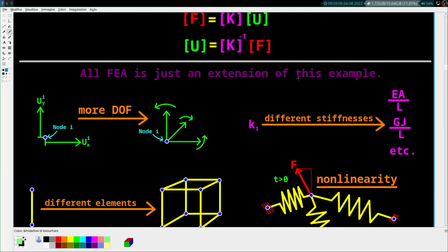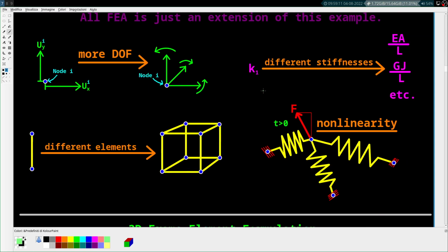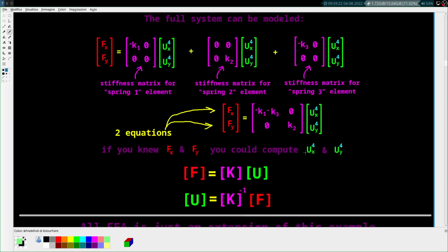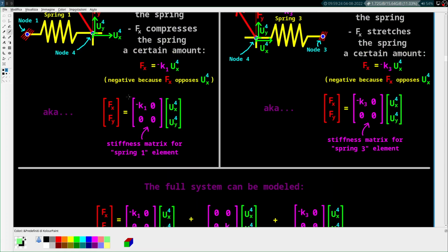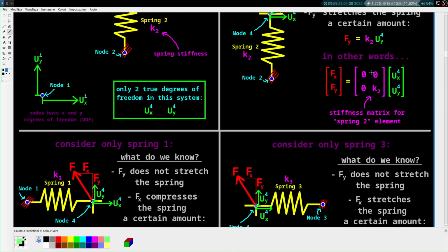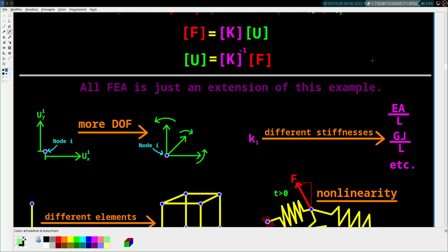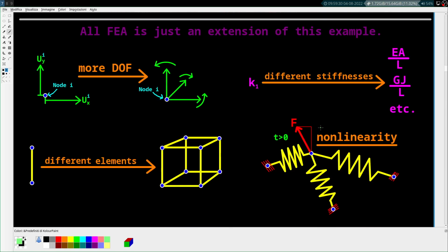So that's saying that if we were to break up the force into pieces, so if it's a 100-pound force, we took it in 10-pound increments, they would have incremental effects on the spring locations, in this node location. We could constantly be reevaluating these matrices with sines and cosines and that kind of stuff. And we can reevaluate the nonlinearity every iteration, right? That would be a geometric nonlinearity.